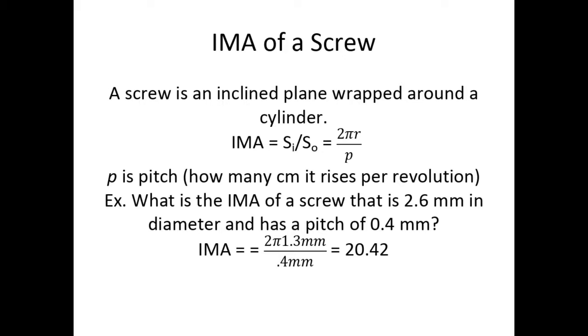And the pitch is 0.4, and you end up getting an IMA of 20.42. So what that basically means is that for every pound of force you use to screw that screw into the wood, it's doing 20 pounds of work.